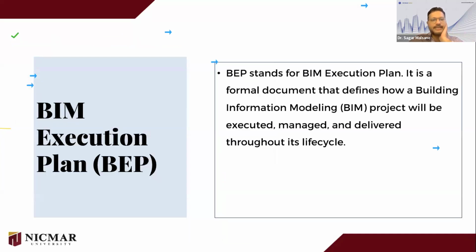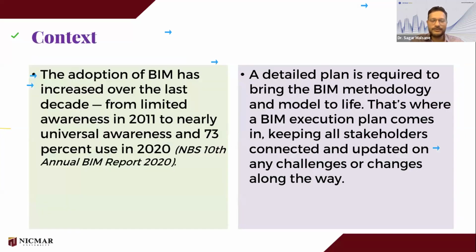Okay, and then you can also utilize the concept of BIM execution plan for procuring all the services of BIM, including sustainability. Okay, so BIM execution plan is a very key document which basically focuses on how a client can procure BIM related services in a very formal manner. So BIM execution plan provides that document that defines how a building information project will be executed, managed, and delivered throughout its life cycle, including sustainability.